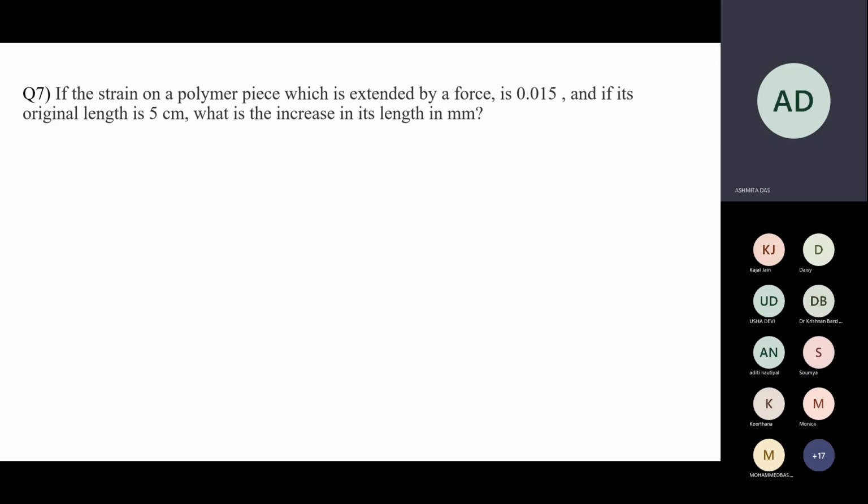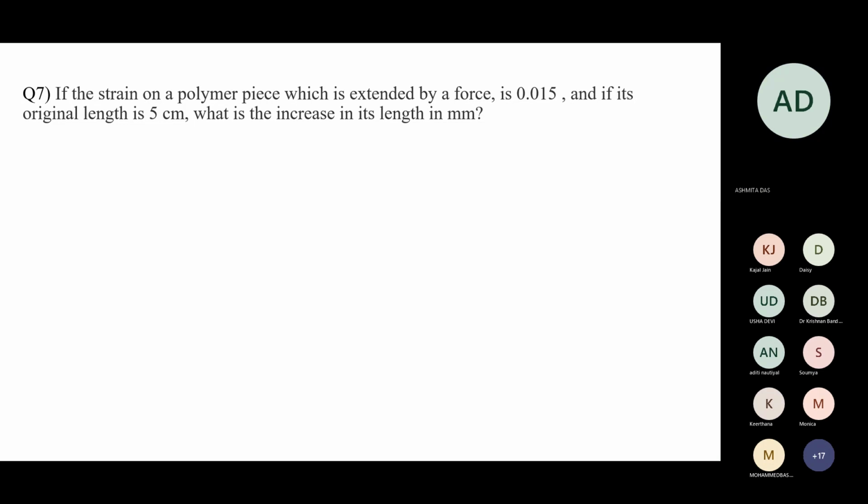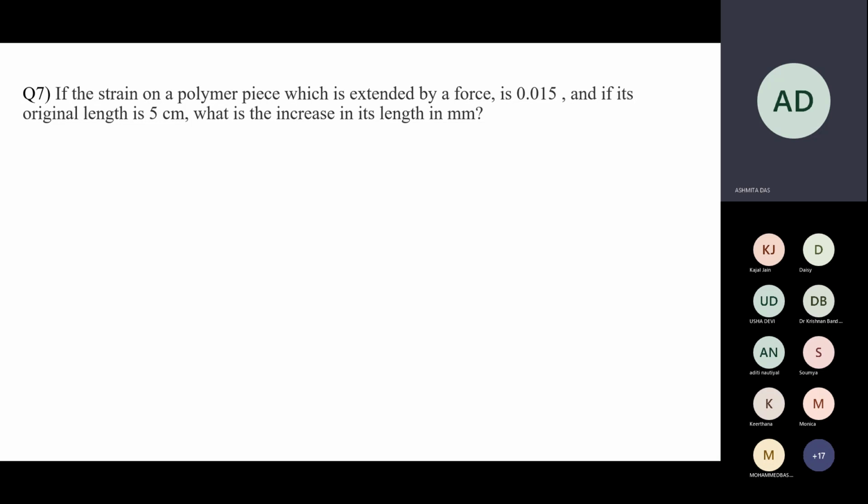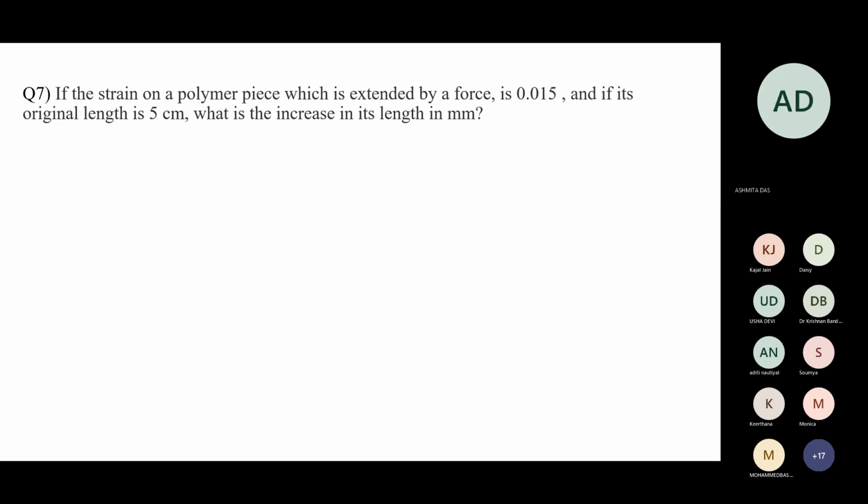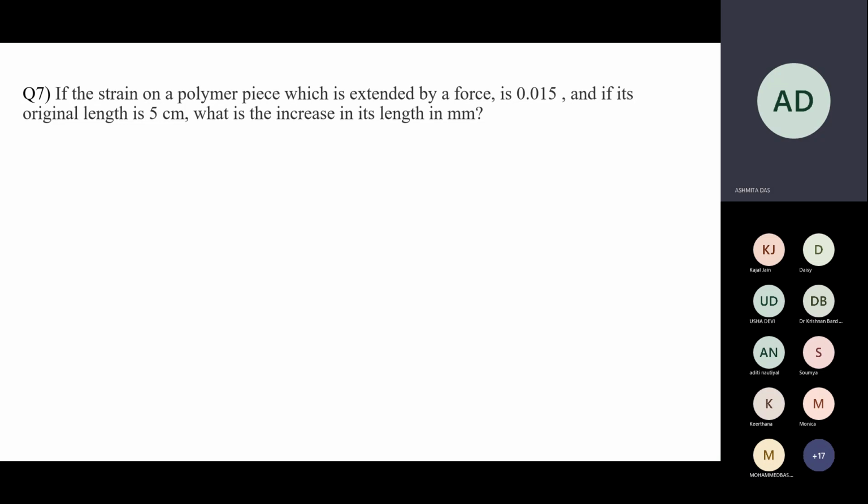So the strain equals, as I mentioned here, extension by original length, or strain equals del L by L. Here del L as per the question is 0.3, and your L as per the question is 250. So del L by L equals 0.3 divided by 250. Okay, so the answer is 0.0012.